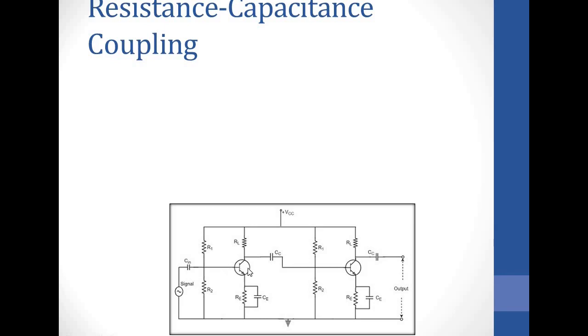When it affects that, it actually affects the operation of the circuit. So you want to stop the DC so that it doesn't pass to this output. The DC from this part is not supposed to flow to that end. So these two DC parts are isolated using this capacitor here.